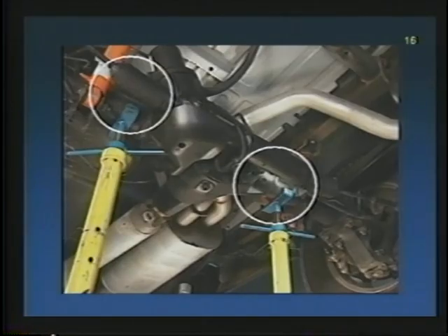Likewise, if you're supporting the vehicle with jack stands like we see, again, just make sure you contact the axle housing. The components back there aren't designed to handle the weight of the vehicle. Keep that in mind. Now, service information does call out where you can get procedures on how to lift and jack any vehicle. If we take a look at the screen here, we can show you where it's at. You can read that, can't you? Well, let me help out, since it's a little small.